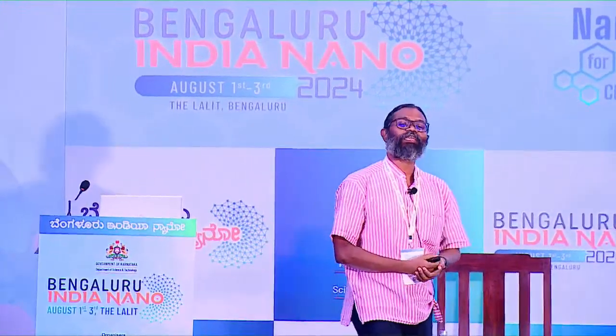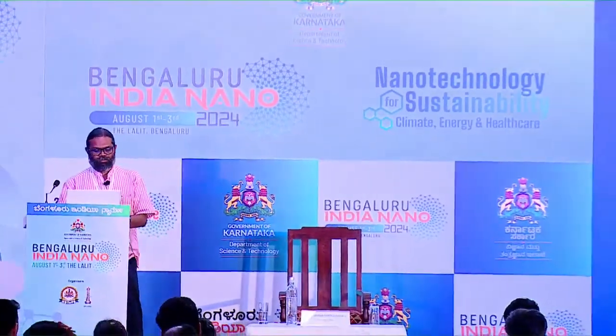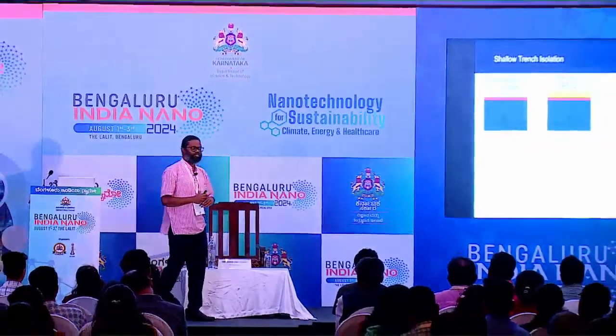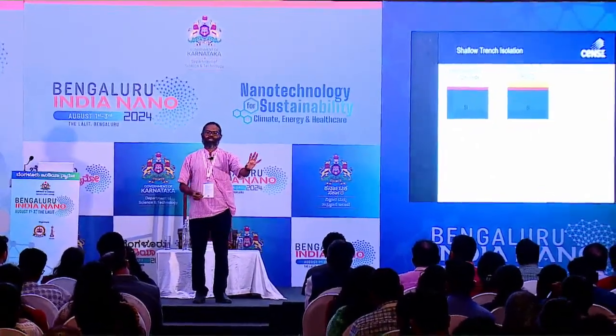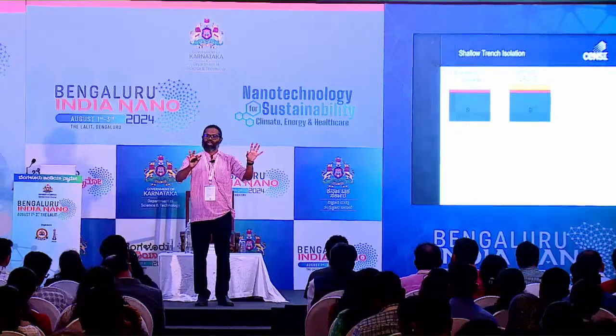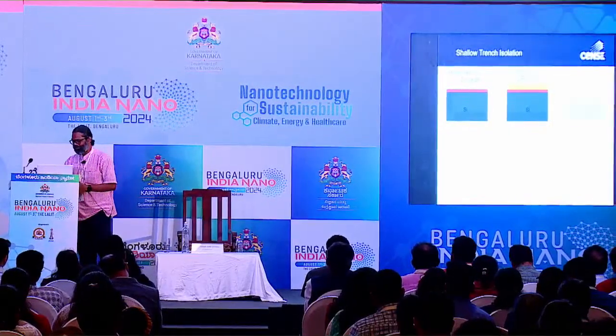And then you come in with silicon nitride, which is again a silicon-based material, which is very hard. Some of you who are coming from a materials background know that silicon nitride is a very hard material, particularly crystalline silicon nitride. If you can do that, it is a really, really hard material. Okay, and in this particular case, we deposit this silicon nitride by using a CVD technique, which is called chemical vapor deposition. So I put in silane that has silicon, and also I put in nitrous oxide. So they react and they form silicon nitride. Okay, again a very resistant material.